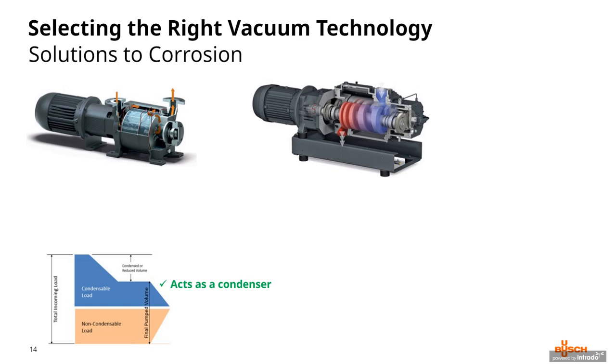So be mindful here not to cavitate the pump with too much vacuum or too hot water. Here's where solvent recovery options are available. A liquid ring pump should be kept with liquid inside, about half full. They're typically installed at the lowest point of the system to allow all fluids to flow in by gravity, excess being removed through a separator.